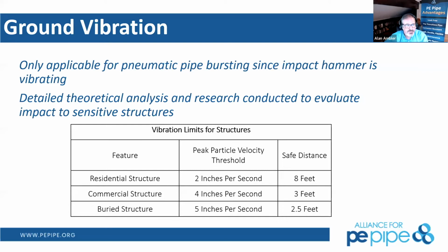But vibration, and this slide title here really shows us and discusses vibration. It is unique to pneumatic pipe bursting. Static pipe bursting simply does not have the vibration associated with that impact hammer. So if we are next to a sensitive structure, you should certainly first consider static pipe bursting instead of pneumatic pipe bursting. And then a brilliant researcher named Dr. Alan Atala had conducted a very substantial study on peak particle velocity and its transmission through soils.